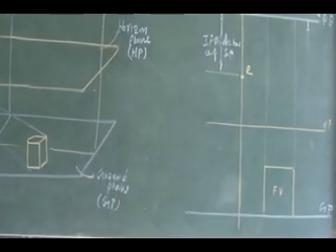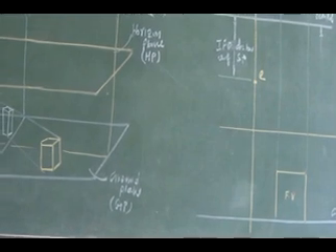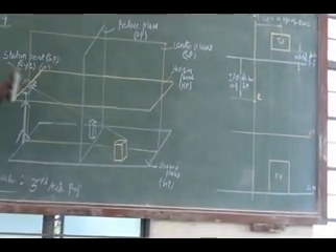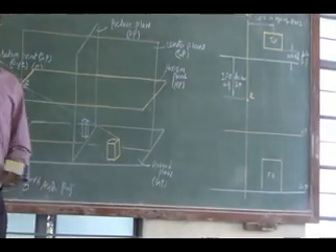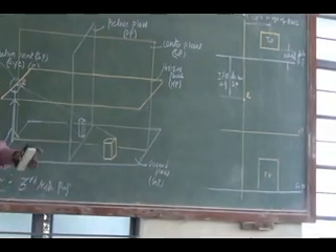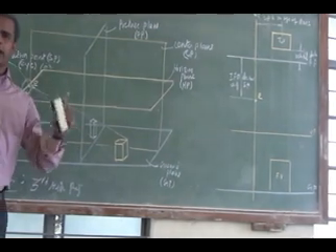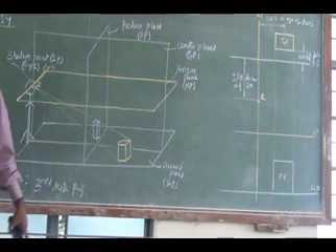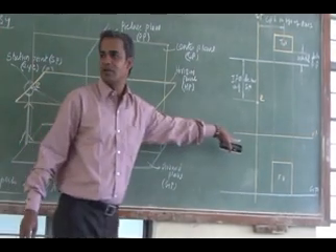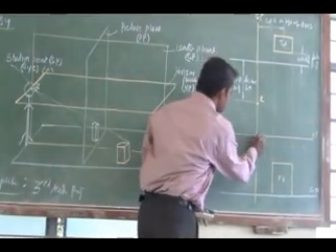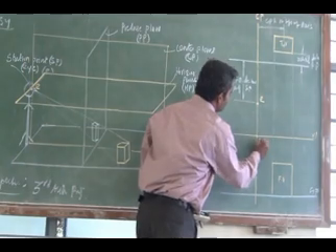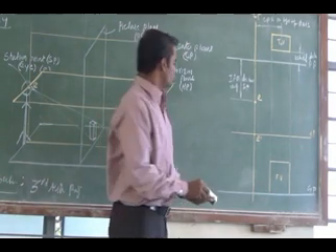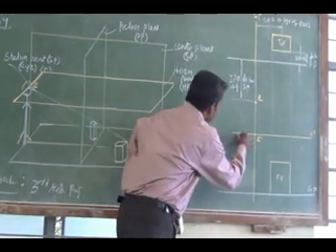Then what about the station point? In the front view I can see the station point also. Where exactly do I mark it? On the center plane. Still, exactly I can mark it, at the point where it intersects with the horizontal plane. So this intersection location is going to be my station point front view, E dash. Right. So what is this height?